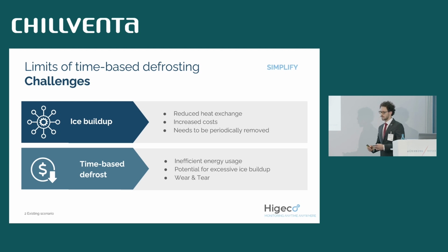Or maybe sometimes we are defrosting not often enough, and this can lead to excessive ice buildup, which then results in problematic food conservation. And in any case, we have problems with wear and tear. So our components need to cycle through defrosting and not defrosting, and this is not optimal.